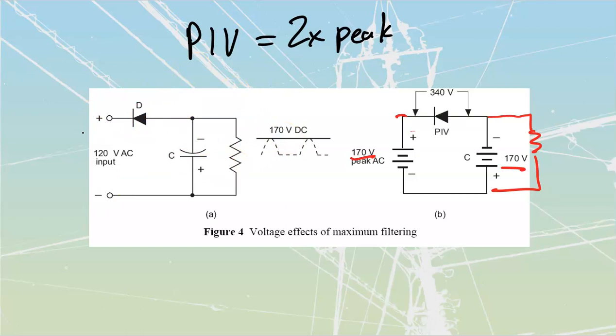Remember that for any of my low voltage caps, we have to be under 50 volts in 1 minute. And if it's a high voltage, we're allowed to take 5 minutes to get that thing down underneath there. If you are unsure, bleed them off. Don't short them off with a screwdriver shaft or anything like that, but make sure that you're using a proper high wattage, high ohmic value resistor.